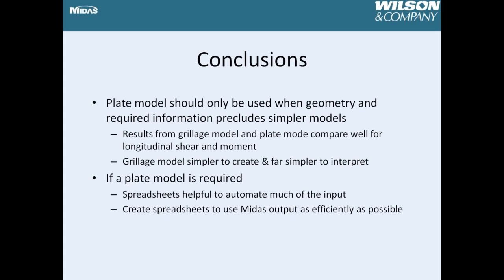The Grillage model was definitely simpler to create and far simpler to interpret. If a plate model is required, I recommend that spreadsheets be used to automate much of the input, especially if you're looking at a bridge like this where the geometry is irregular. It's probably the easiest thing to do that in a spreadsheet rather than trying to do that in the graphical user interface. Another tip is to create spreadsheets to use the MIDAS output as efficiently as possible.